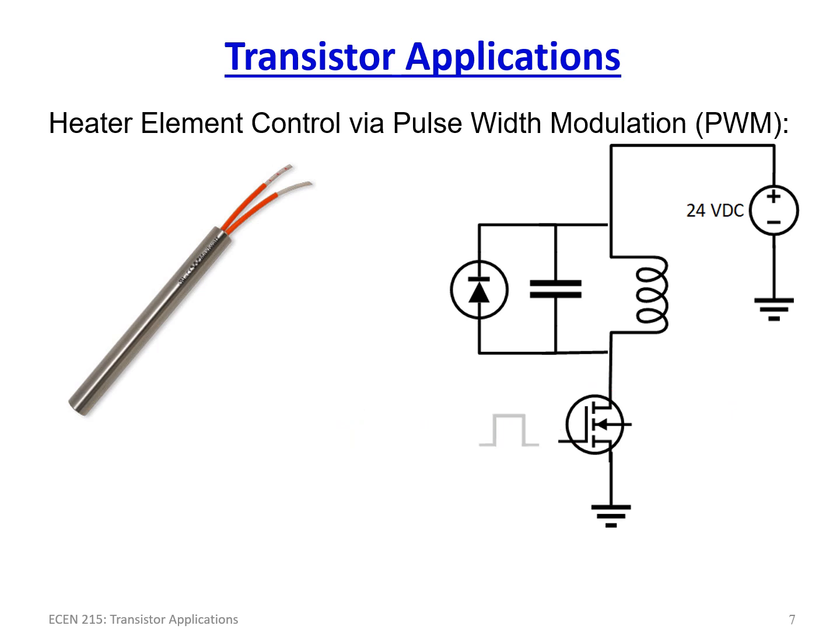Now, you'll notice it talks about pulse width modulation. So I can turn on and off the heater. Now, in a lot of applications, we want to actually control the amount of heat we're introducing proportionally. You could control the current that you're driving through here with an analog circuit. So basically, we inject a current I into this, and the amount of heat generated is proportional to that.